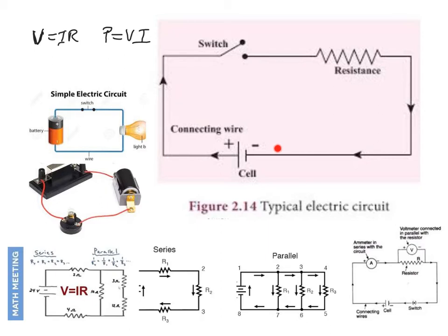So voltage is an energy-related concept, and when we talk about voltage, you'll see in a minute that we always talk about the voltage difference between 2 points. A voltmeter always attaches at 2 points, and it measures the electric potential difference between those points. So if this is a 6-volt battery and we put our meter leads at these 2 points, it'll read 6 volts. If we reverse the meter leads, it'll read a negative 6 volts. And that means that the battery is a source of energy at the level of 6 joules per coulomb.